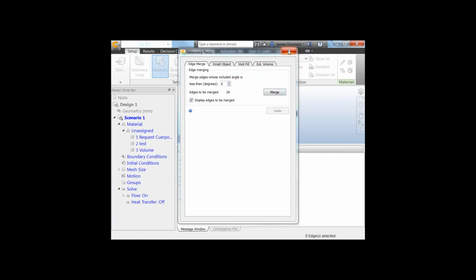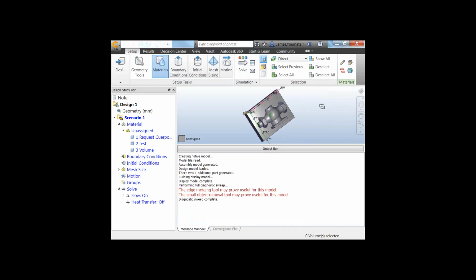All right, and I wasn't kidding when I said it's probably my third time opening CFD. So you'll notice that, yep, there's our model. And, all right, Todd, where's the inner void? You're going to have to hold down Control and then hit the middle mouse button on the back wall, the rectangular block, and spin her around. And there it is. Boom, already there. And you can see that it was done in the output bar as well. There was one additional part generated.